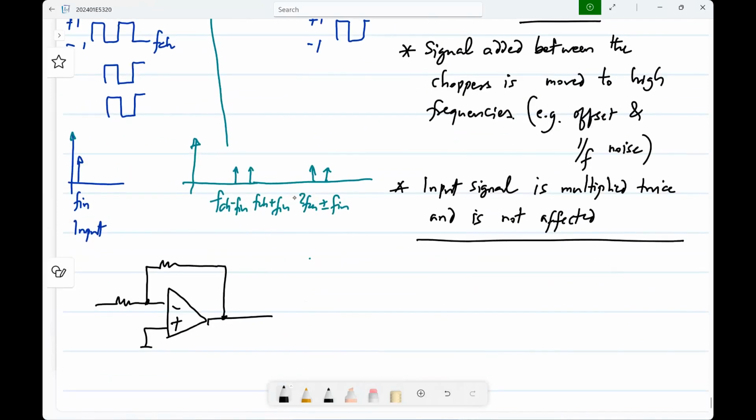So let's say you make this inverting amplifier and you want to have a gain of -1. Okay. But what is the problem? These two resistors are different in general, right? There'll be mismatch between them. And again, you can try to make the gain closer to -1 by making the resistors larger and larger. But clearly, if the variance in the gain was, let's say, 2% and you want to make it 0.2%, you have to increase the area of the resistors by 100 times.